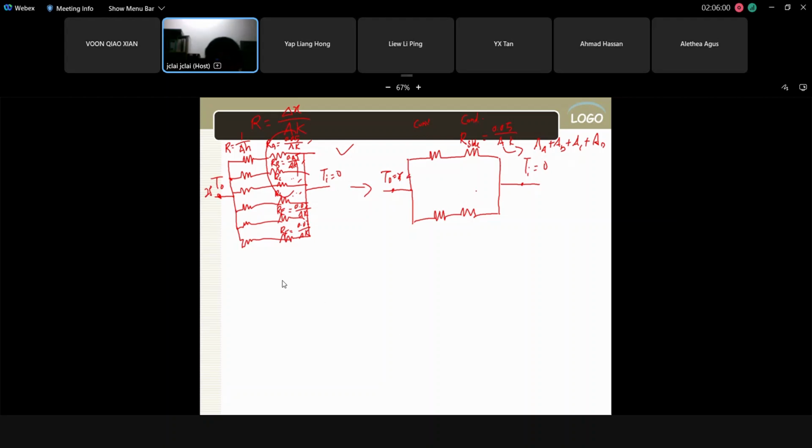Okay? And number 2 here. These are our top and bottom, right? Thickness is 0.02, so that's why they can be combined together. Here is A for top and bottom, which equals AE plus AF. Actually these two are the same, but if you understand the concept and draw this, it saves your time, because you don't need to calculate all this one by one.